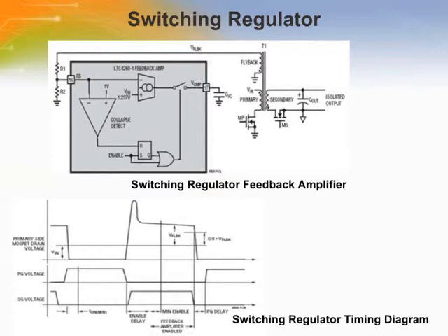The LTC4268-1 includes a current mode converter designed specifically for use in an isolated flyback topology employing synchronous rectification. The LTC4268-1 operation is similar to the traditional current mode switchers. The major difference is that the output voltage feedback is derived via sensing the output voltage through the transformer. This precludes the need of an opto-isolator in isolated designs, greatly improving dynamic response and reliability.